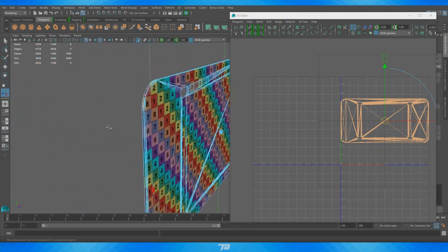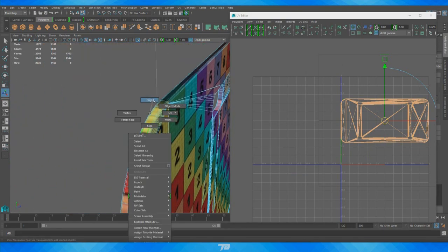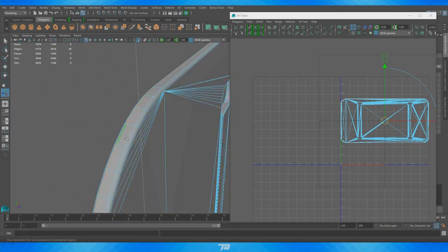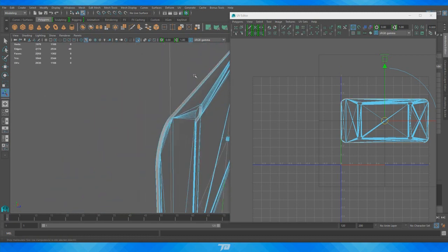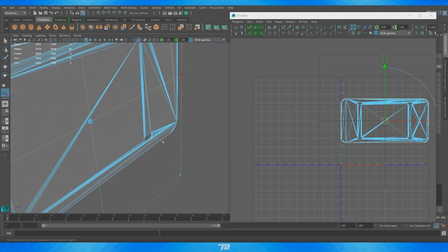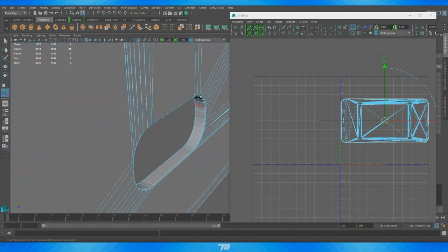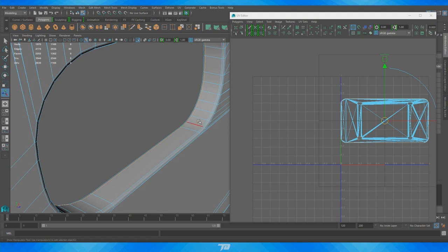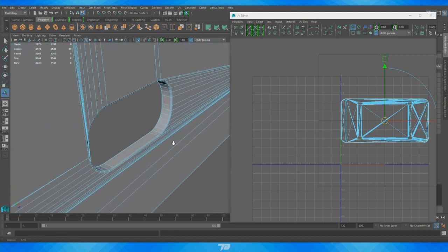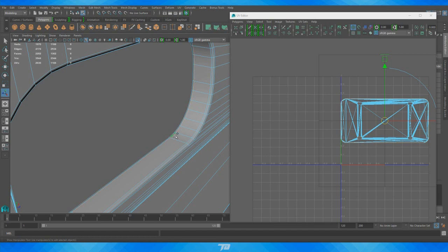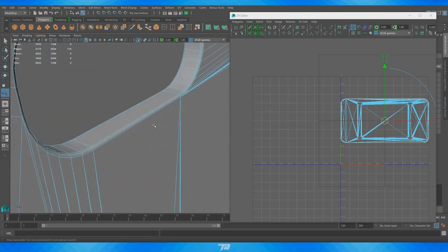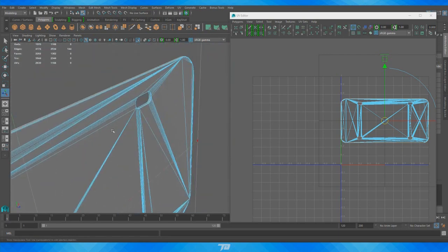So now what I'm going to do is select the edges that I want to cut this by. So I'm just going to double click this edge here. I'm going to turn off textures just for this part so it's a bit easier. Double click this edge here just so we have something along the actual edge of it on the outside. But that's not quite enough. We also have to select edges on the inside of here to cut it, simply because that's just the way it works. If we cut it just by the outside, it's still attached here on the inside, so that's not going to do. So I'm just going to shift double click these inner parts and just make sure it's consistent. Make sure you're cutting the same ones here. It really doesn't matter too much, but the consistency makes it go to that extra level. Shift double clicking these all.